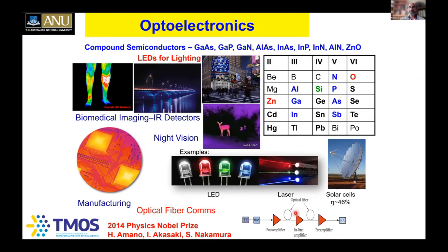And it turns out the optical fiber communications don't operate in the visible region of the electromagnetic spectrum, and typically we use the near-infrared region of the spectrum of 1.3, 1.55 micron wavelengths, at 1300 or 1550 nanometers, because that's where the lowest absorption and dispersion takes place in optical fibers. That's why we make use of these ones.